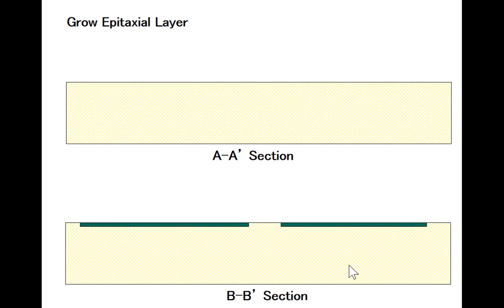Next thing we do is grow an epitaxial layer. What's an epitaxial layer? Mr. Day. It's a way that you're able to grow the substrate and have the same lattice structure and increase it. Great. So it's a single crystal extension of the material underneath. So we make it thicker. And we're going to make the epitaxial layer N-type. And this is a thick epitaxial layer we put on.